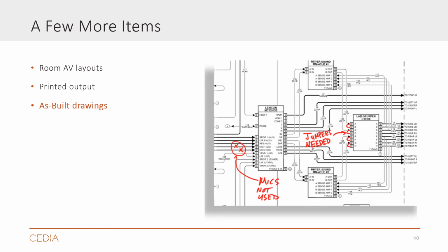As-builts are the result of marking up your job site master drawings, often in red, that reflect any and all changes that were made, usually out in the field. These marked up pages are then used to update the originals to as-built drawings. And no matter what direction you go or how you document your systems, make these changes. You will save time and money if you do.